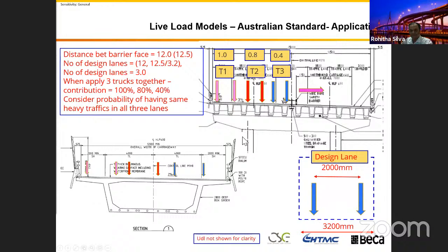You get the control. You draw sketches, draw the cross section. Look at, if you position this one in this loading, if you apply in here, it will give more load in here. It will produce that one. Those load cases are sketched down. Put it down on paper and then give them numbers, load case 1, 2, 3, 4, 5, 6. Do your analysis, go back to your results, check your number one, you specify this load case will produce the maximum force on your exterior girder, maximum sagging on your cross beam, and maximum out of balance in your foundation.